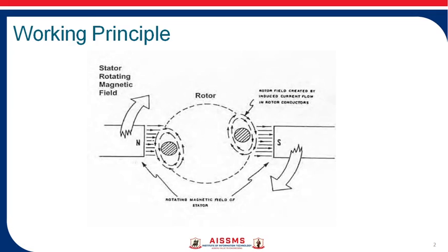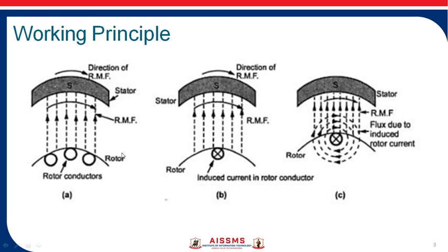At that instant, when the rotor is stationary, the stator flux generated by the rotating magnetic field is rotating. Obviously, there exists a relative motion between the rotating magnetic field and the rotor conductor, and when this rotor conductor cuts the magnetic flux, that generates the EMF, or EMF gets induced in the rotor, and this is nothing but electromagnetic induction.